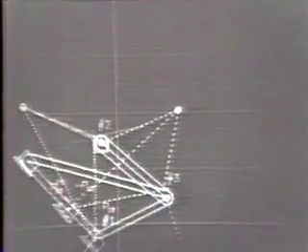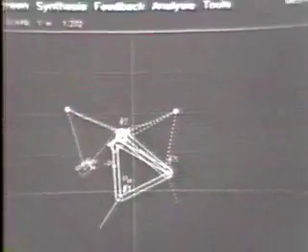Now the designer has gone back and is changing the slider position on its locus, and you can see that the coupler triangle instantaneously is updated to show the new possibilities.